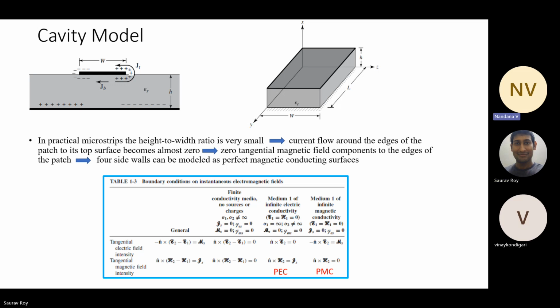So from that basic model both are designed. But here you see we are ignoring the other portion of the substrate. We are taking only the metallic layers. But in the patch antenna, there is substrate beyond the metallic patch also. Outside the patch there is substrate that we are ignoring. We are taking only the substrate in between the metallic layers.